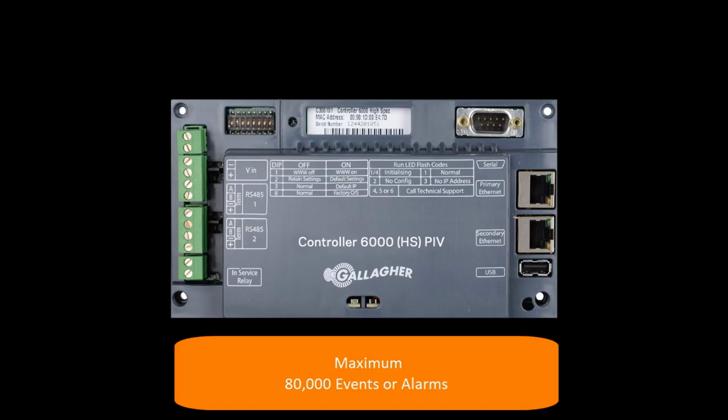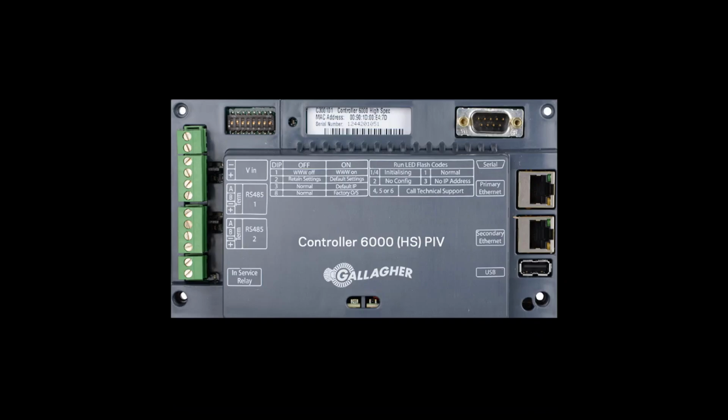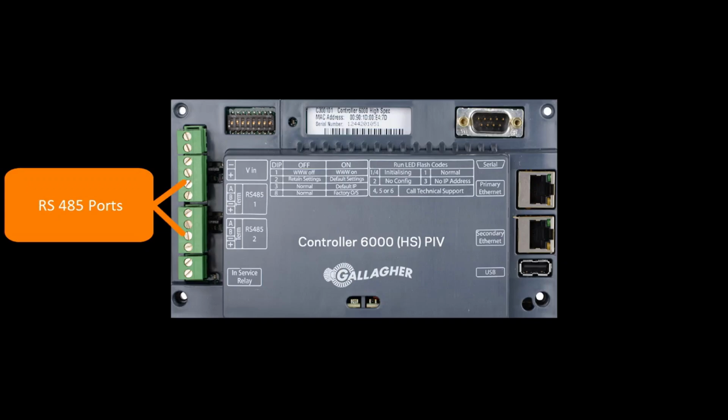When network is re-established, the controller will push these events and alarms through to the SQL database so history remains intact. The maximum number of doors per controller is 10. Adhering to this limit ensures the site is operating within recommended specifications, which is important should Gallagher technical support be required. Both the standard and the high-spec 6000 controller provide two RS485 ports, which are located here.